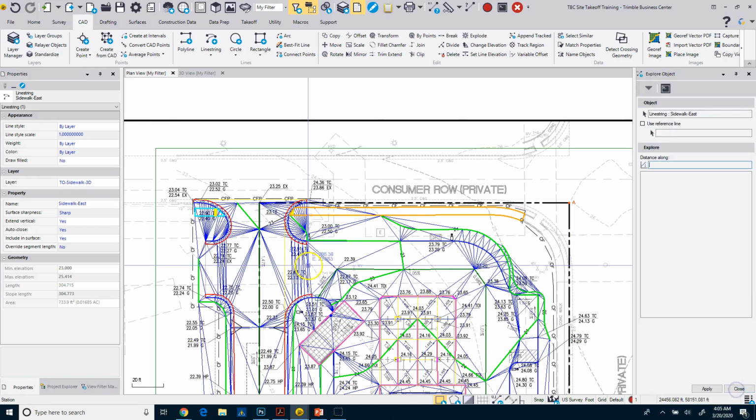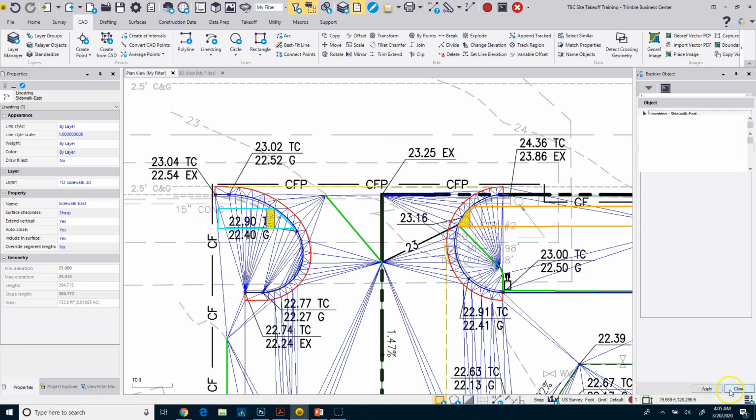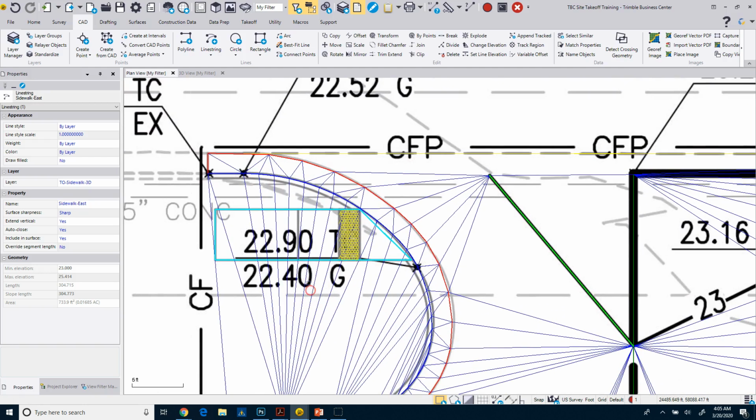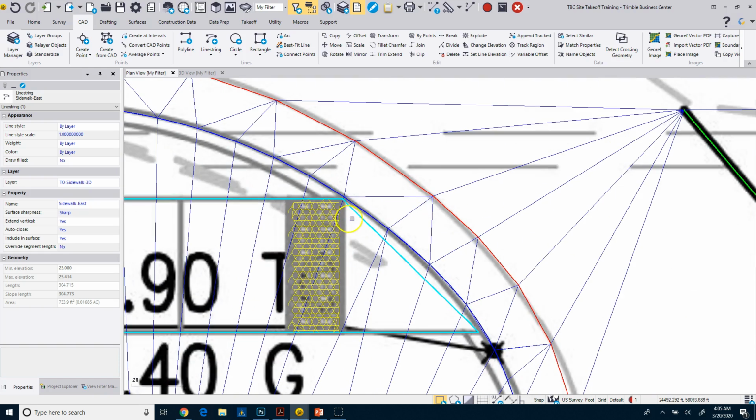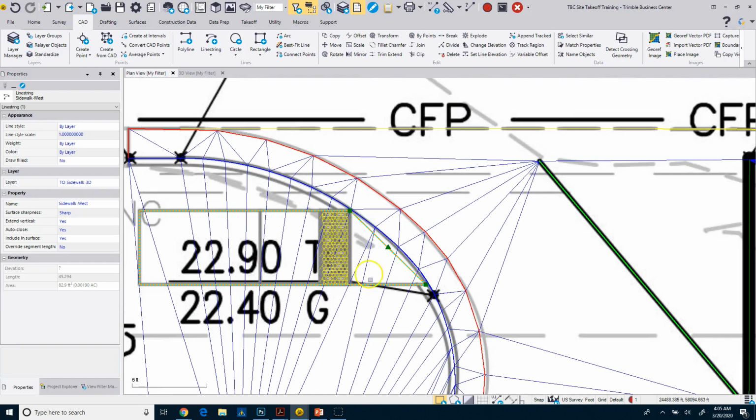So I'm going to have to repeat this process for this sidewalk over here. So I'm going to close this guy out, and I'm going to do the same thing over here. I'm going to use the elevations from my curb line, go set elevation points at 8% here, and then I can set these elevation points at 2%. So we'll go ahead and do that. I'll show you again how I'm going to do it.